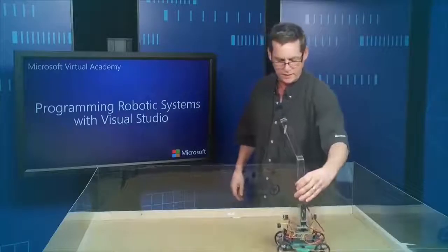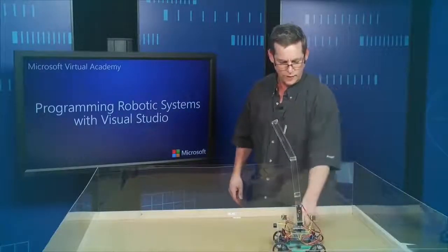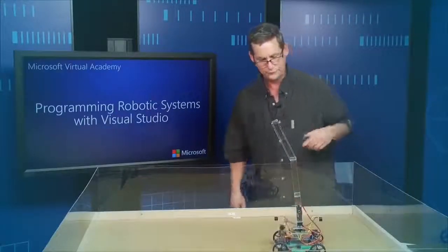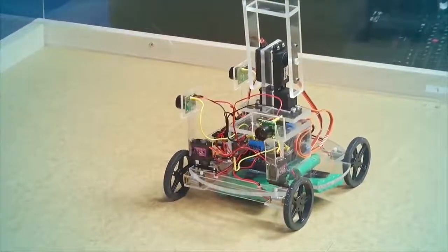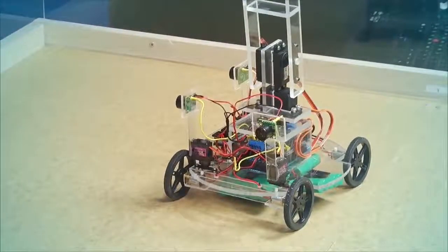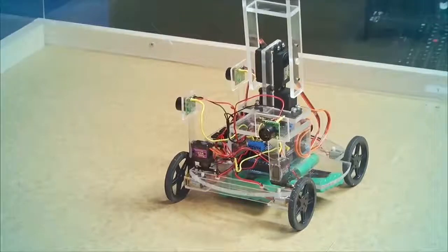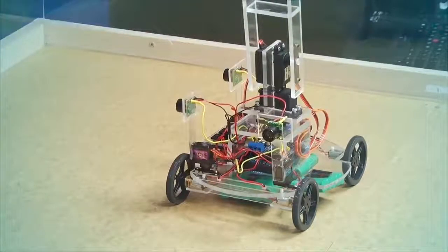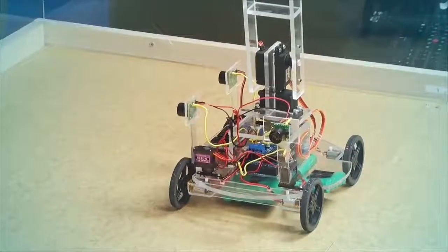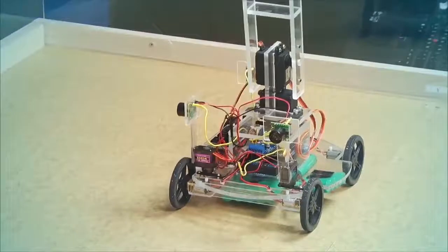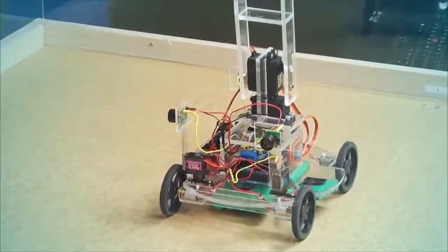This one we said is semi-aware, right? That's what we said. So what he's going to do, he's going to initialize as well. Now he's looking around his area. He's got these ultrasonic sensors. He says, oh, hey, here's a wall over here. I think I need to align to that wall, because what he wants to do is map his area. Right? So now he takes his readings with his sensors, and he's saying, hey, one's bigger than the other, so I'm going to spin a little bit until both are reading about the same thing. Then he's going to start moving towards the center of the area, and then he's going to read his coordinates.